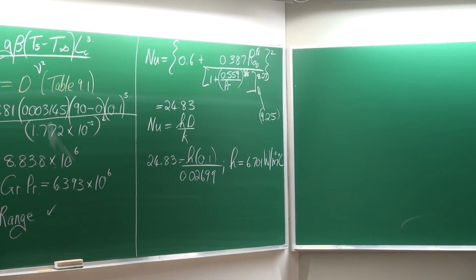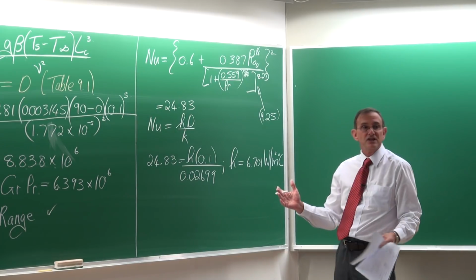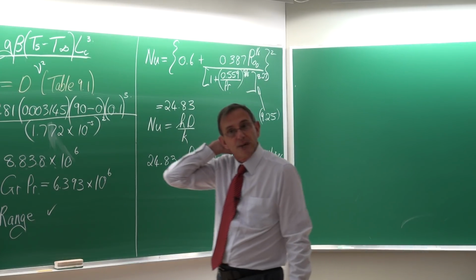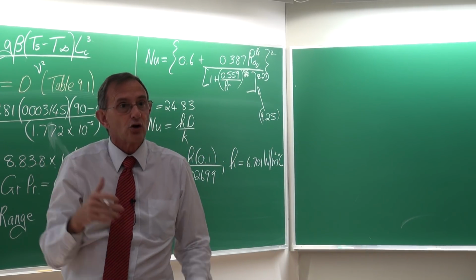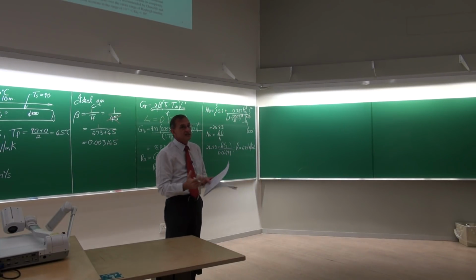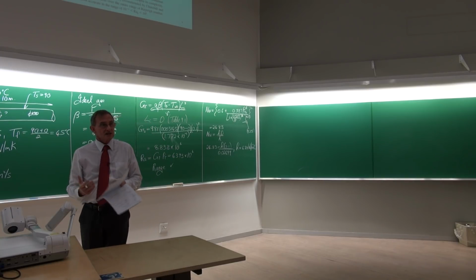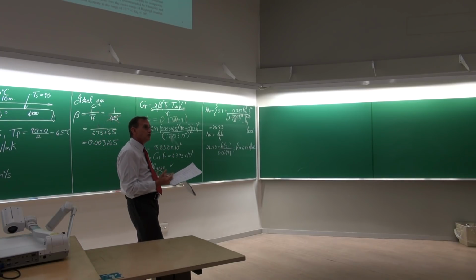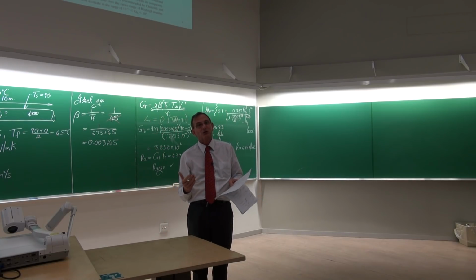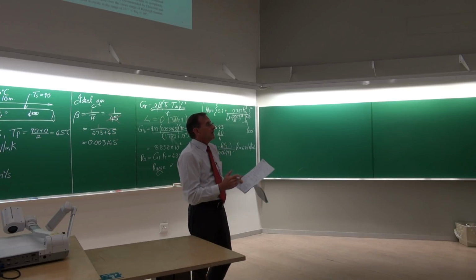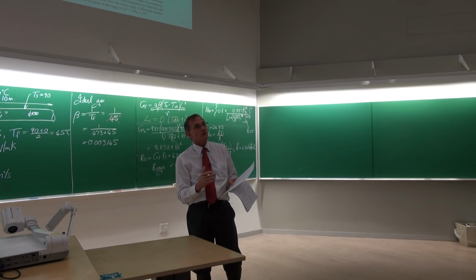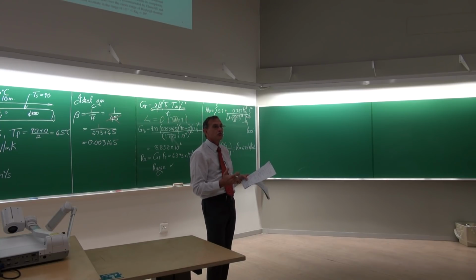It's also quite important that when you start doing all these calculations, you take a look again at chapter 1, where the concept of the heat transfer coefficient was introduced the first time. They said something very important, and that is that in natural convection, the heat transfer coefficients are normally low. Typical order of magnitude is about 10. Okay? Then when you've got forced convection, typical heat transfer coefficients are of order of magnitude hundreds to 1,000.